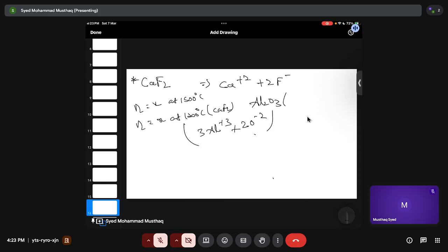In slags you can have different types of oxygen. One is totally bonded, in the form of silicates, bonded with your silicon. Another is the free oxygen ion that is readily separated from calcium.